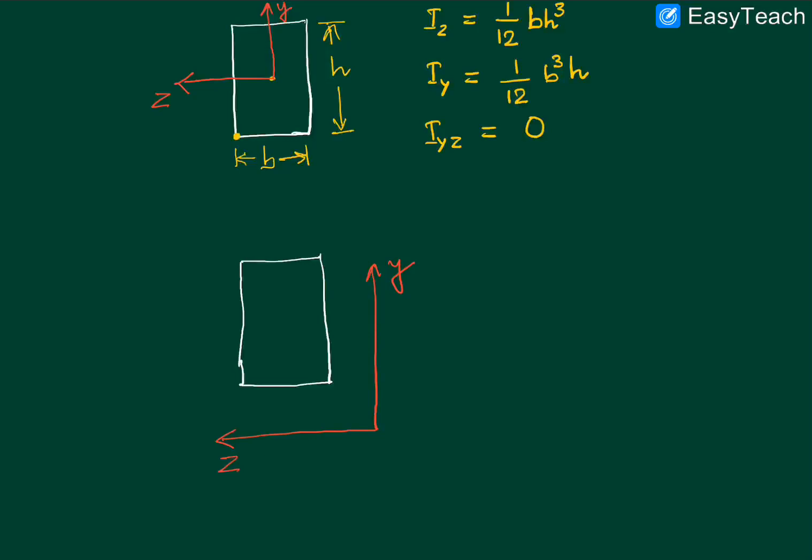So the motivation for this particular discussion is that some real world engineering beam cross sections would be composed of a composite of such rectangles. So we'll discuss that in the next page, but for now we'll just quickly take a look at what happens to the values of Iz and Iy for this particular setup. So we have the same kind of breadth and height as before, but very importantly, we recognize that our centroid is still here,